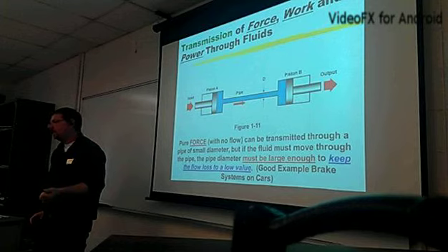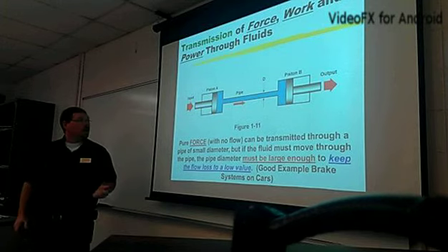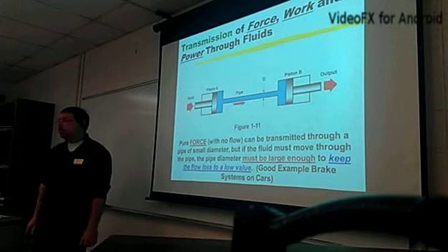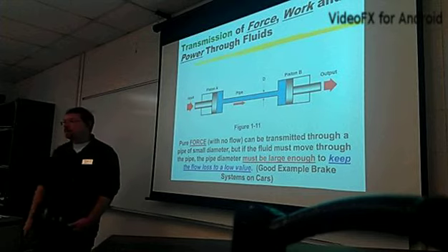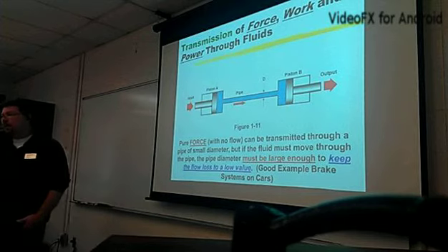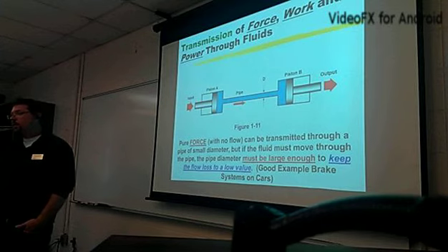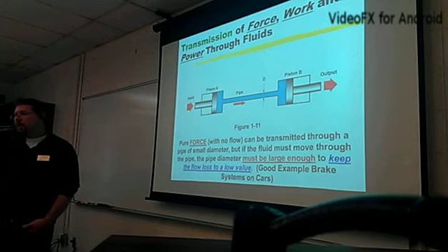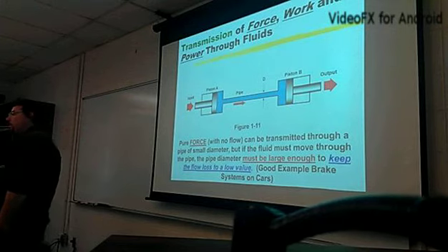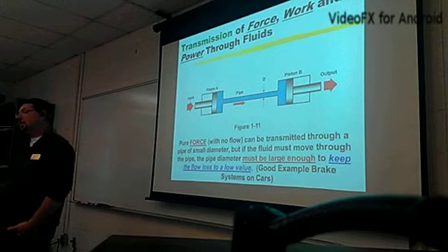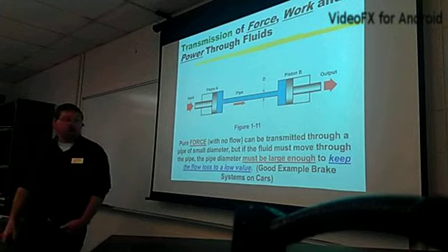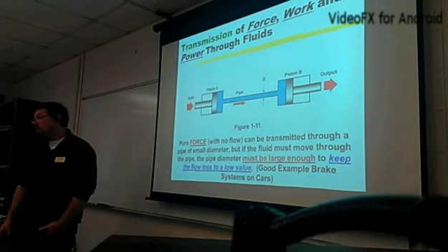And you're asking why that is. Well, there's friction going through this pipe. Make sense? Friction through the pipe. So we lose a little oomph to friction. And guess where that friction in turn goes: to heat. The heat in turn is carried through the fluid, hopefully all the way back to your cooling system on your reservoir, and you get the heat out, because if you don't get enough of the heat out, it can get hot enough to flash fire. I mean, it's rare that would happen. Most times stuff will melt and fail before then, but hydraulic systems make heat, just a given,